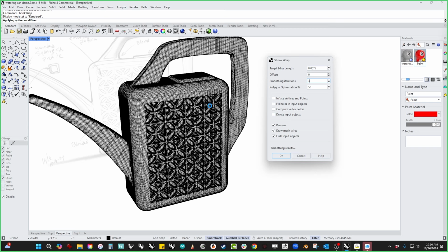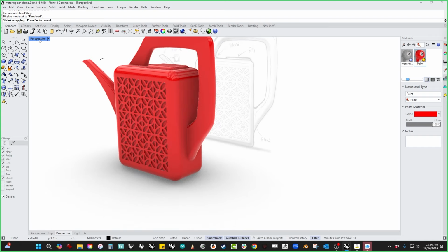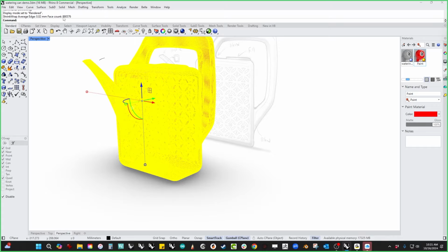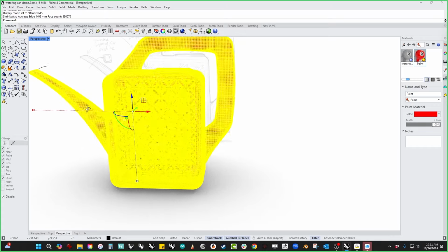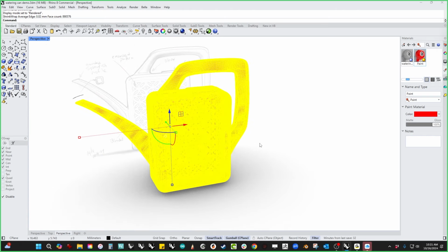Now, keep in mind, the goal here, now that we've decided, is going to be 3D printing, so we wanted a shelled part, and so our output is going to be mesh. And we're going to call this good. If we look, give it a second to finish. There we go. So we've got 890,000 polys in this. That's a big model, but it's not insane.